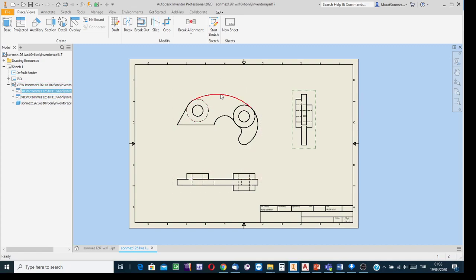The distance from the tip point of the front view to the upper margin, and from the tip point of the top view to the lower margin, those distances should be equal. From this limiting point to the left margin distance, and from this outmost boundary to the right margin distance, should be in the same order. It is a format requirement.